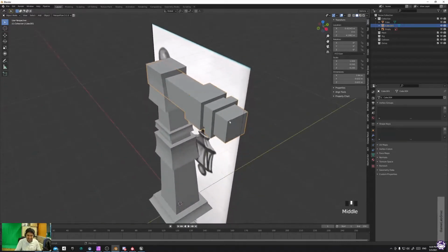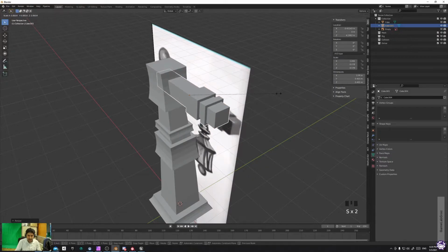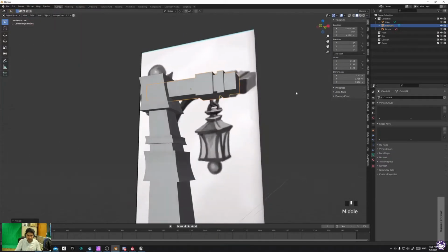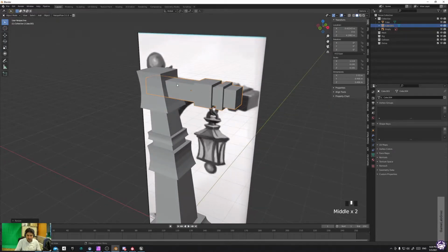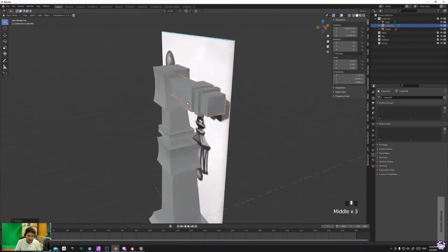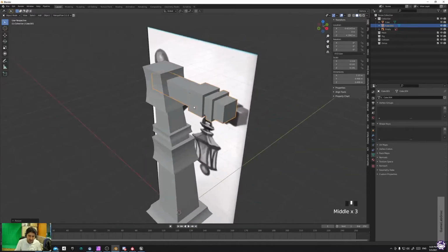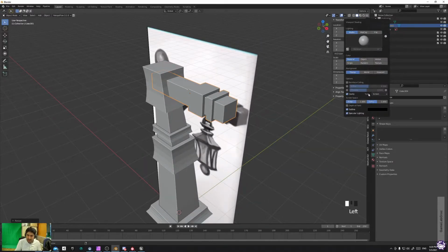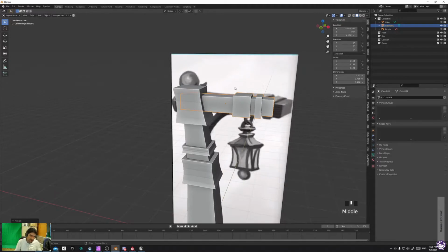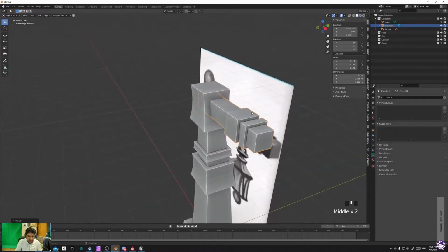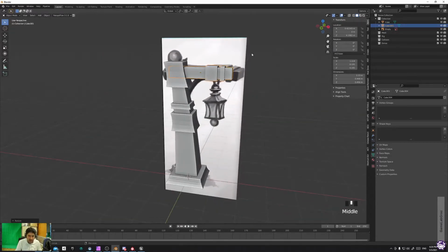We can see that this part is a little bit heavy. Let's reduce the size to get a better feeling. Perfect. Sometimes you see that the colors are not very clear and it's just creating misunderstanding when you are looking at the model. It's better to activate the cavity, both world and screen together. It will add ambient occlusion, screen space ambient occlusion to your model, and it helps a lot to see your model.